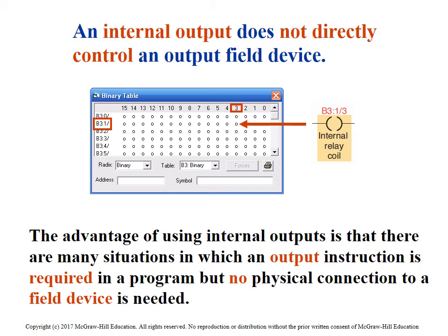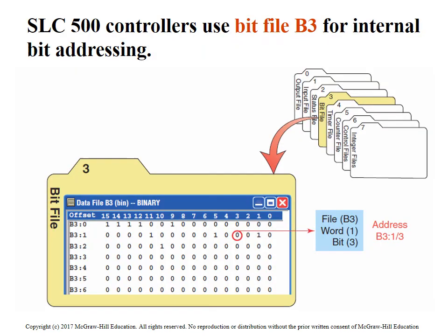And then once we got our logic all developed, then we go back and we turn on the outputs based on those internals. So we use the internals as our logic, and then once we've developed all our code, then we go back and we turn on contacts from these internal relays to turn on outputs, and we'll be getting further into that in the future here.